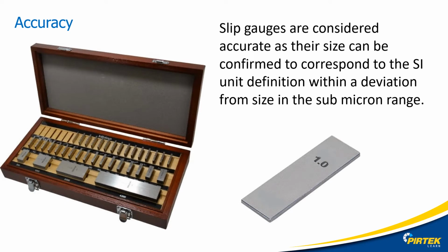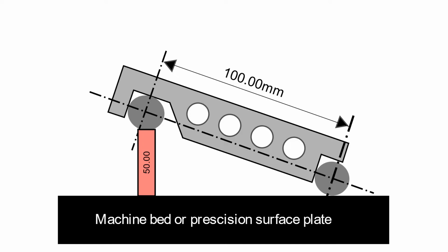Here we use slip gauges. We discussed slip gauges and gauge blocks in year 1. Here's another application for using these precision blocks. Using a combination of slip gauges, we create a stack that add up to 50 millimeters, and we put it underneath the left-hand roller.